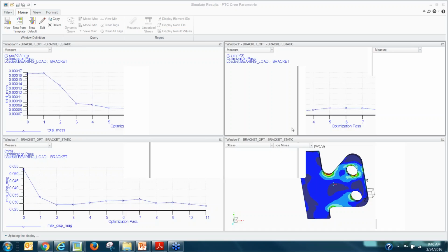So all you really have to do is check whether your config is set up in such a way that it's pointing to a system color file, or syscol file, that you prefer. Then it should take it automatically. So I would check your Creo 3.0 after installation. Is it still pointing to the same system color file in the config that you use in Creo 2? In that case, it should work fine.